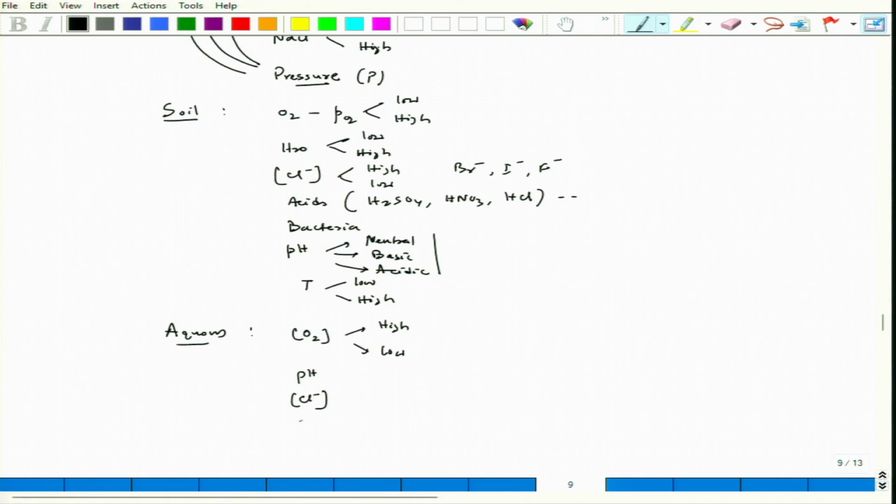Now, then we have several other ions present like H2SO4, HNO3, other salts. Whenever these salts are present, what does it do? It actually improves the conductivity. Now, interestingly, one way to protect metals and alloys is to increase the resistance path for the charge transfer or electron transfer. Okay. So, if we have a very high resistant electrolyte, definitely the corrosion would be less.